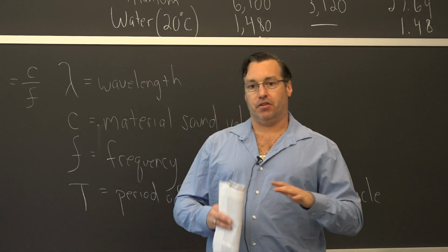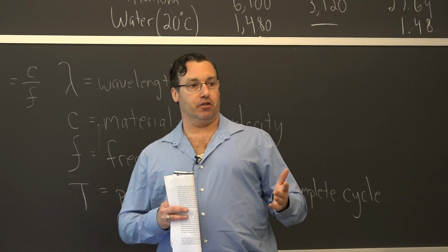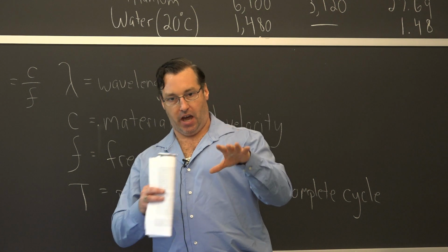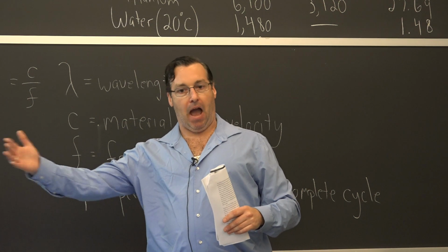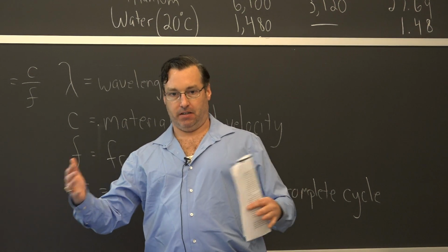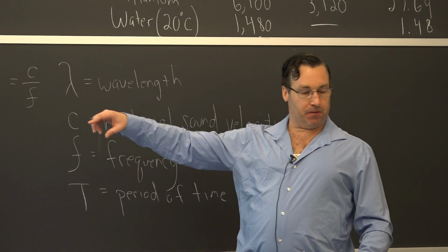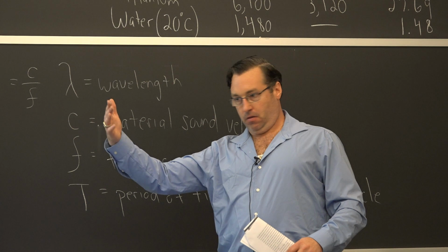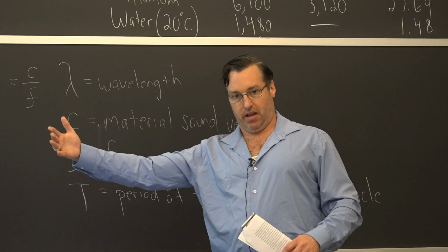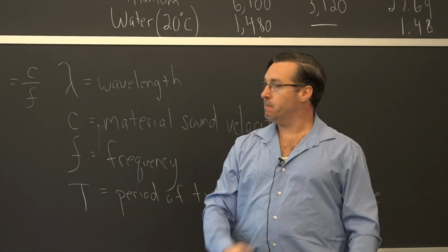Some of the terms you'll hear in the ultrasonics industry are pulse echo, pitch catch, back wall reflection, and time of flight diffraction. So it relates to the time it takes for that sound wave to go through the component you want to test and come back to the equipment.